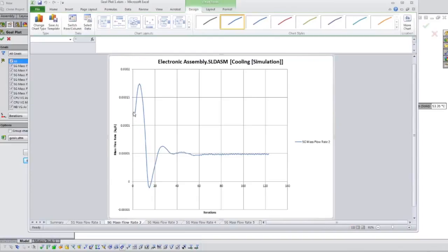These guys were kind of under the gun. They didn't have SolidWorks Flow Simulation. They didn't really have time to take the software, get it in-house, and learn how to use it. So what we did is worked with them from an analysis consulting perspective. We took their problem, we updated the model, we built the models for flow simulation specifically so we could move things around if things didn't work the way we expected to, and then really evaluated the flow inside the model, making sure the velocities were what we needed and were close to what we had in the previous model to really understand how the problem works.